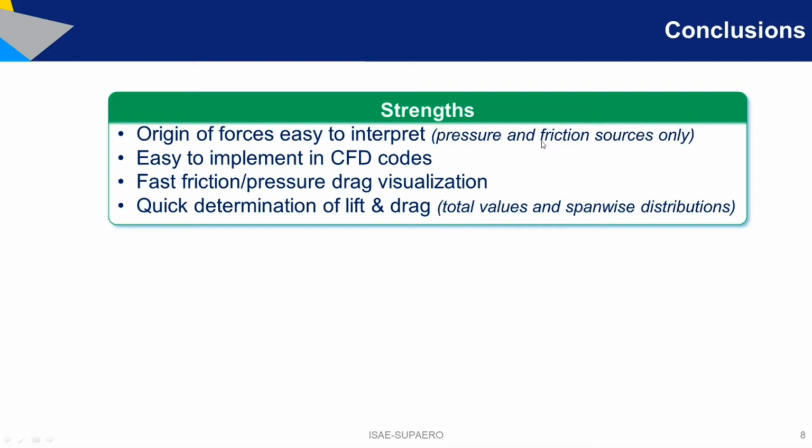That's a very good point. Then the other advantage is that this method is quite easy to implement in CFD code, and in fact in all the CFD solvers, the drag and lift values they show each time you perform a CFD convergence are based on the near-field method.